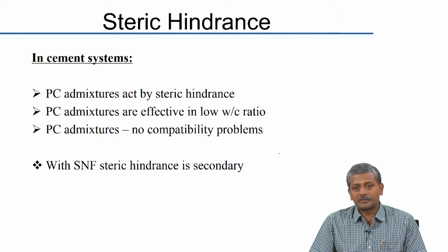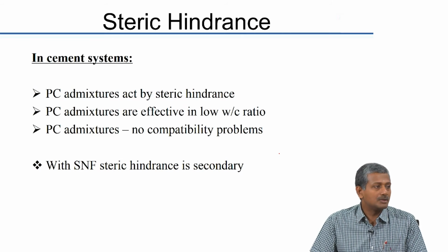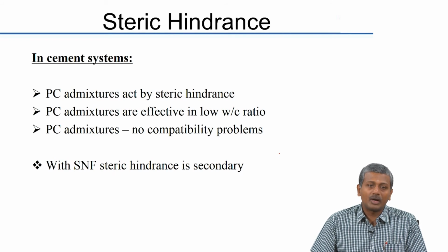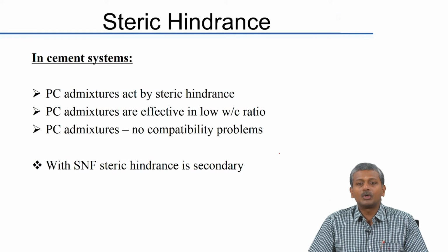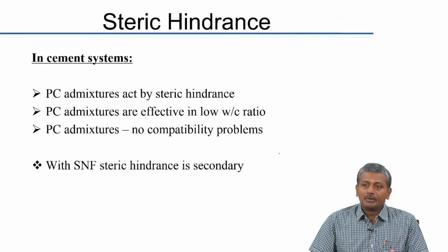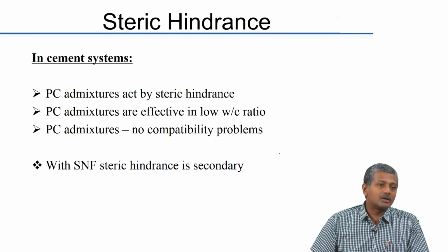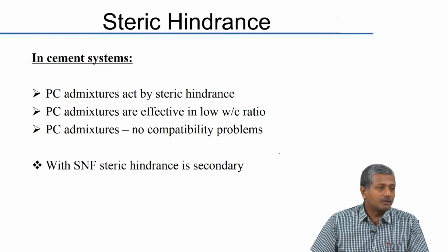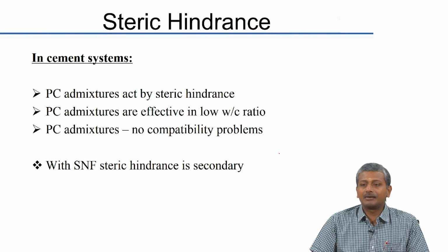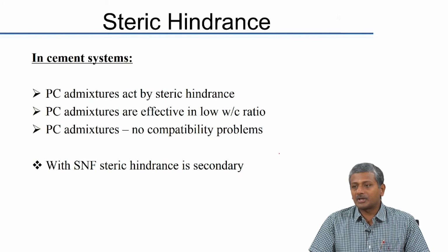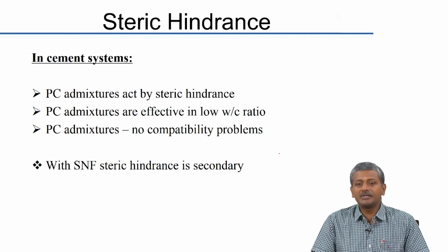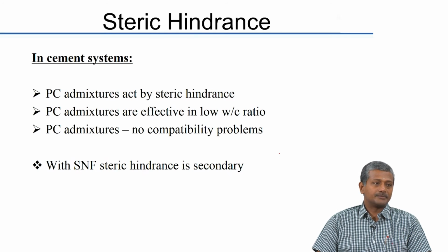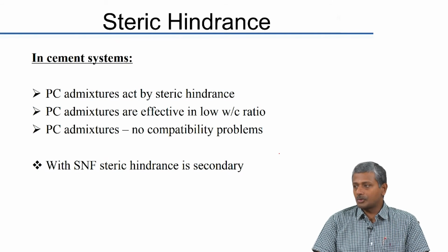So, polycarboxylic ether admixtures or PCE admixtures act by steric hindrance, because of which they are effective at low water cement ratios, especially when you want to produce very high grades of concrete or ultra high strength concrete. You have to rely on polycarboxylic ether admixtures, and generally they are not known to have compatibility problems. With sulfonated naphthalene formaldehyde, if you are providing a very high molecular weight chemical, you may still get some steric hindrance, but it is secondary. The primary aspect there is the electrostatic repulsion and not the steric hindrance. Steric means related to the structure.